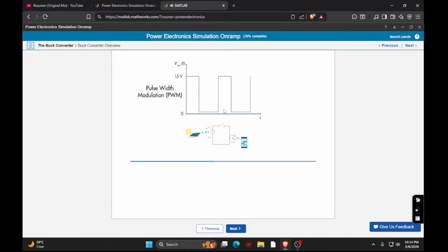For a PWM signal, the fraction of the time that the signal is high is called the duty cycle. Okay. When the duty cycle is constant, the average voltage across the switch is just duty cycle times the period. So now we have an average output voltage that is lower than our input voltage. But wait, the maximum voltage is still higher than our load, the phone, can tolerate. Plus, these fluctuations don't make a particularly useful signal.